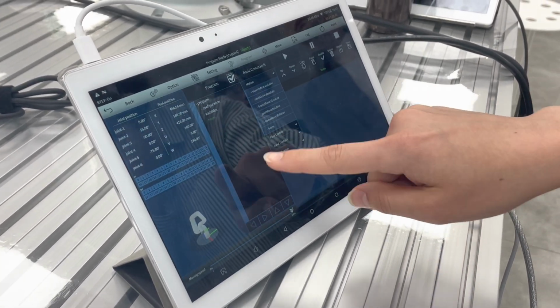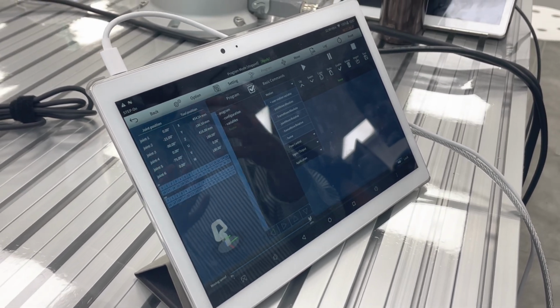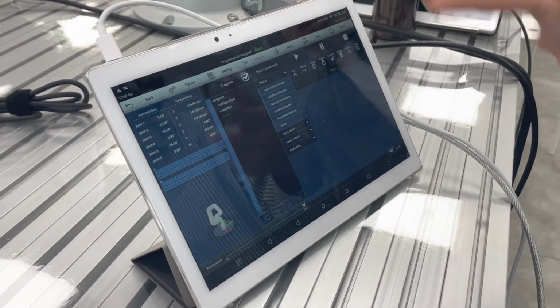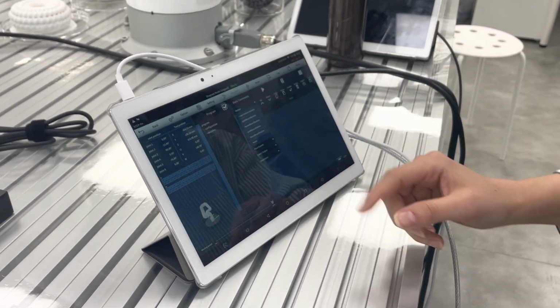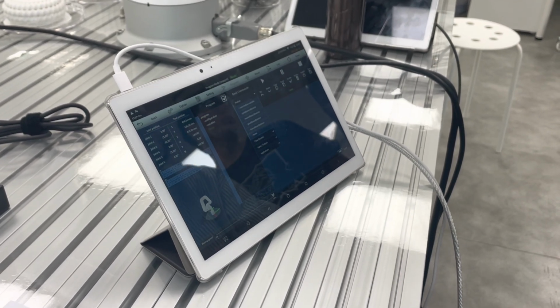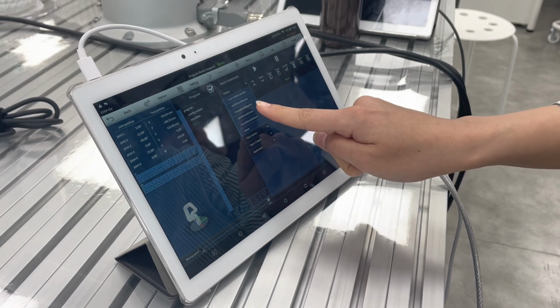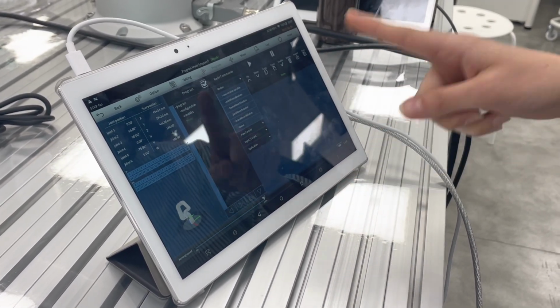Sometimes you want to add 10 tons of movements here, and you want to deactivate some of them and check other things, so you can just enable or disable some of them. But we have 4 different movements here: joint move absolute, frame move absolute, joint move relative, and frame move relative.